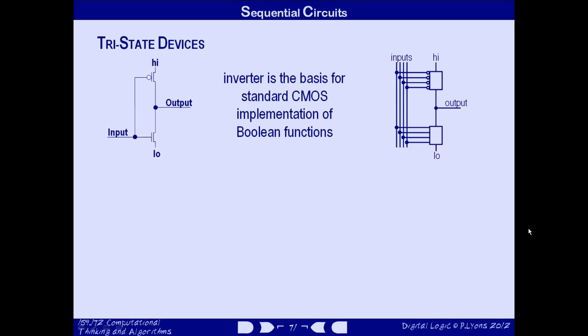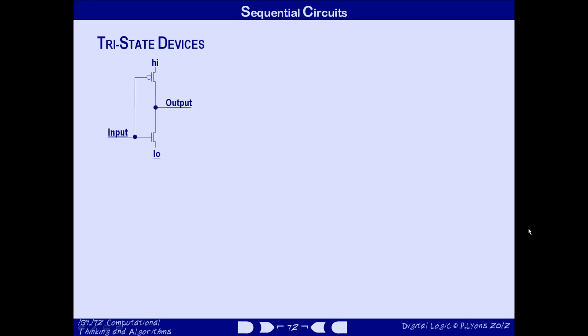To turn the inverter into a tri-state device, we have to be able to isolate its output wire from the high and low voltages. We'll add a control signal called output enable to the circuit. That will operate an active low transistor so that when OE is high, the output can't be connected to the high voltage power supply, whatever the value of the data input.